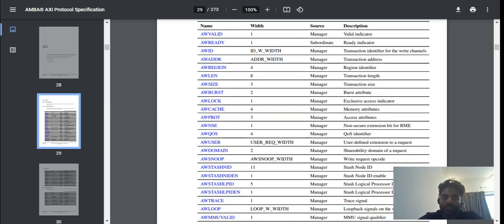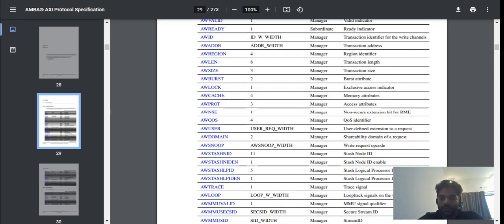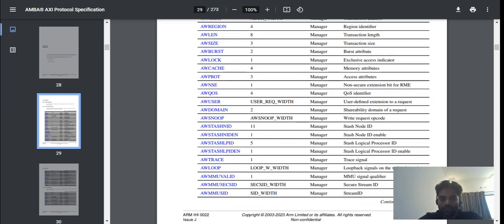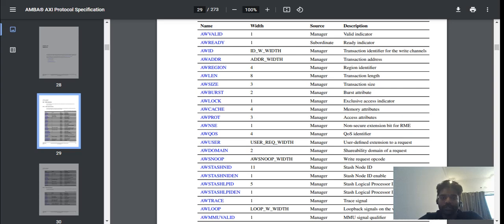So these are the different features. What is the size? What is the burst length you want? You can set all these things up. There are other features too. You can see many signals are there, and you can choose based on your application. You can leave the remaining signals unconnected also, it won't impact anything. So the main features you can start using: what is the length you want? Once you send the first address, how many bits of data do you want to transfer. That's the transfer length, the transfer size, and the burst type. These are the basic use cases.